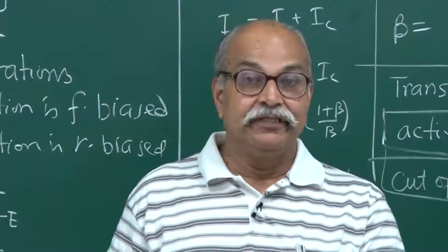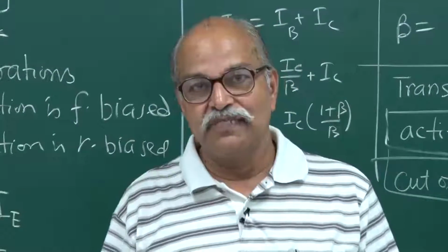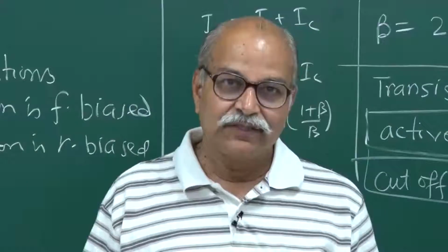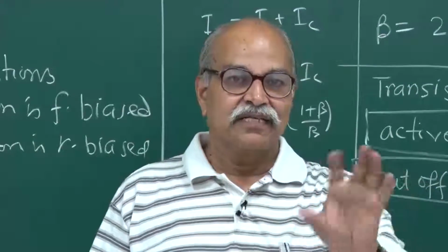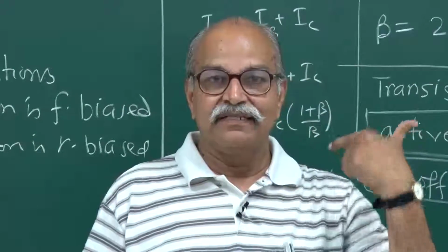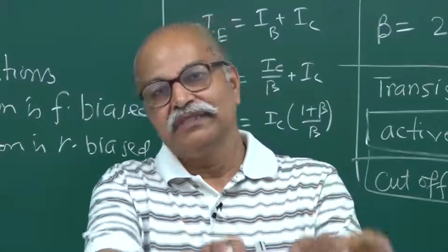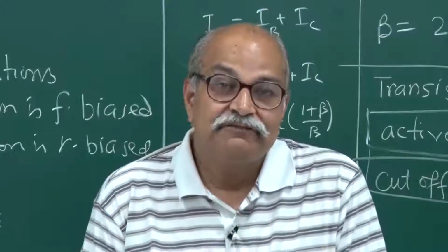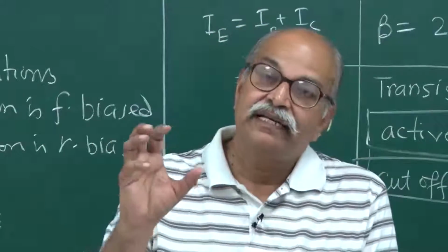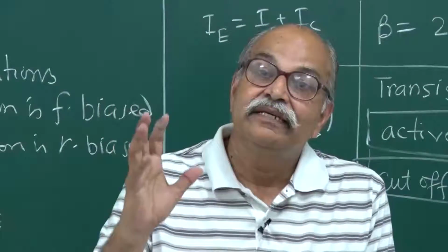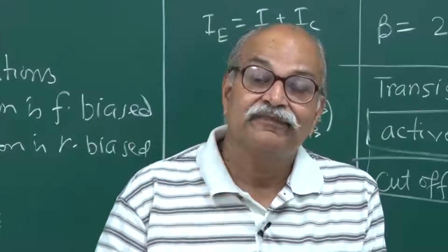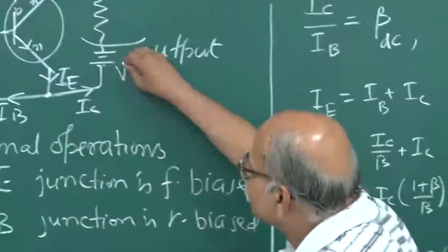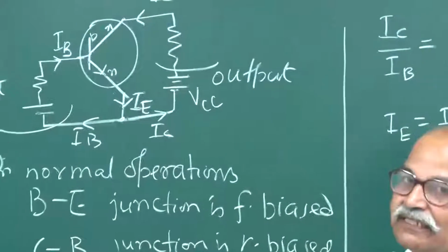If you apply some, say, 5 volts, 10 volts, 8 volts at this collector base junction, good. Whatever electrons are coming, correspondingly that alpha factor is there, so alpha times those are drawn into the collector. But what if the biasing of this collector base junction is very small, is weakened? We apply a small VCC here. This is VCC, remember.